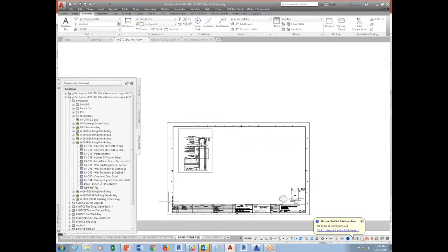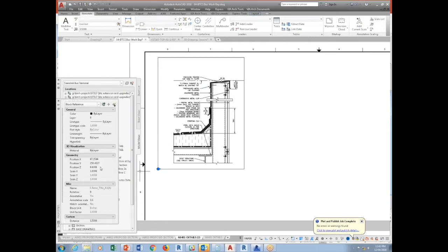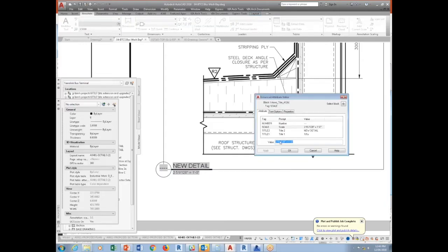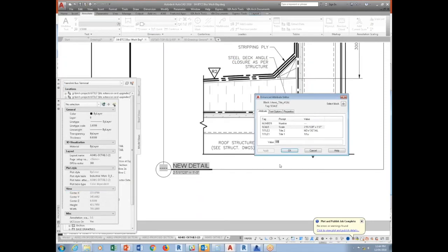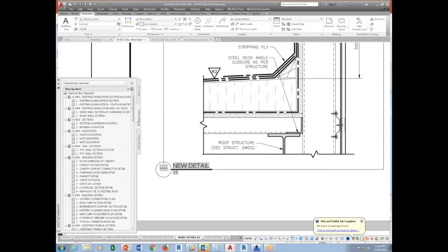For you guys, it's similar to how Revit behaves, correct? So it takes that detail, you just create a view, and then you just plunk them in there. And then, yeah, for some odd reason, this one is in Imperial, so I have to scale everything up by 25.4. But if you have a template, this would work with the Imperial. So I have to go edit this field and change it to 1 to 5. So this is 1 to 5. Now, you can change the name.